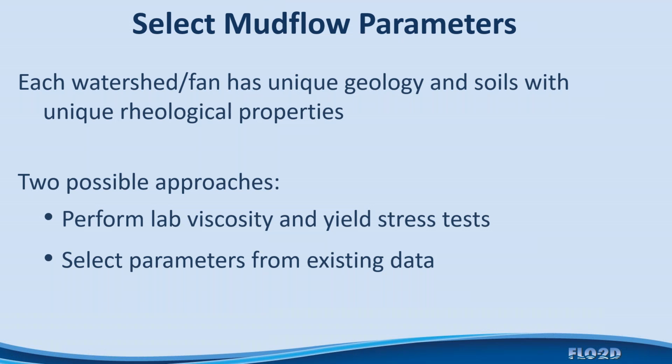So for each study that you're going to do in a watershed or alluvial fan or an area that has mud flow characteristics as deposits, you should go into that watershed or fan, learn a little bit about the geology and the soils and what unique rheological properties they may hold in discrete conditions for that particular watershed.